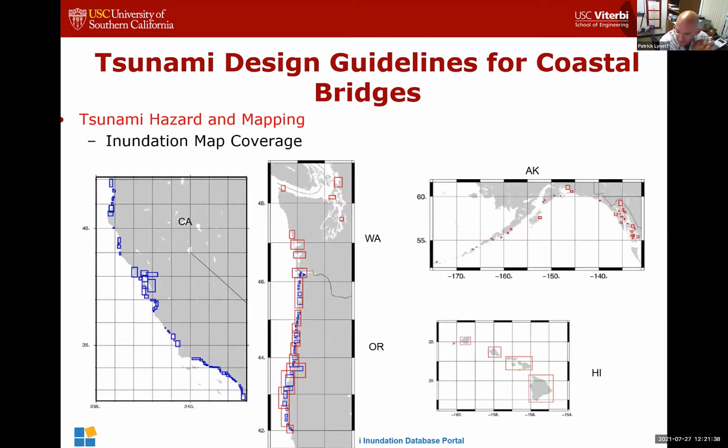All right, and so then with that offshore hazard information, like I said, we're going to select a set of earthquake scenarios which match the offshore tsunami hazard that we're targeting. So we're going to look at that 975 offshore hazard amplitude, and we're going to pick a set of earthquake scenarios that are close to that offshore tsunami amplitude. And then we're going to run it with our traditional tsunami models with nested gridding to some level of refinement for inundation. What you're seeing is the grid coverage for our 5 Pacific states.